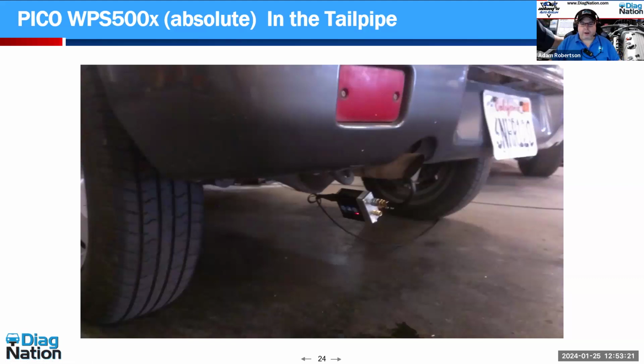Now, well, Adam, why did you use an absolute pressure transducer in the exhaust? Because it's what I had on me. Well, why did I do this test? Does anyone want to guess why I did this test? Why did I perform this test? Do you know what I need to determine? That little bump. Is it a misfire or isn't it?